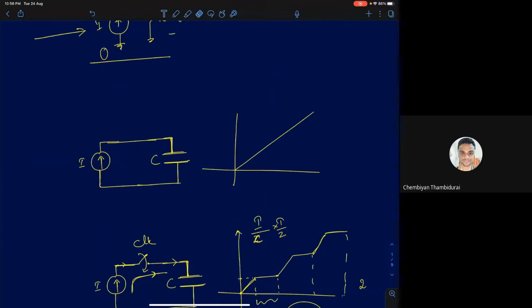On the other hand, consider a capacitor and a current that is charging it. We know a capacitor acts like an integrator. The voltage at any time instant across the capacitor will be the incremental voltage due to the current charging it at that time instant, plus the initial or previous voltage stored across the capacitor. So a capacitor has a tendency to accumulate voltage. It acts like an integrator. An accumulator or an integrator stores the previous voltages.